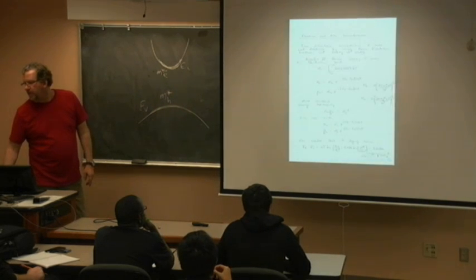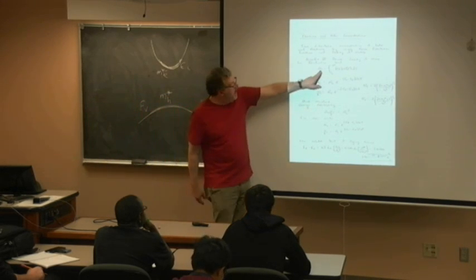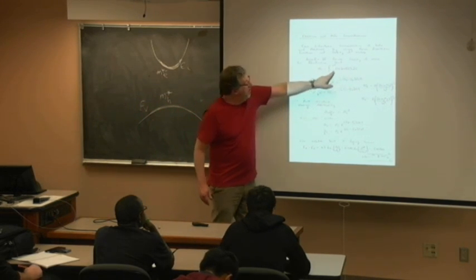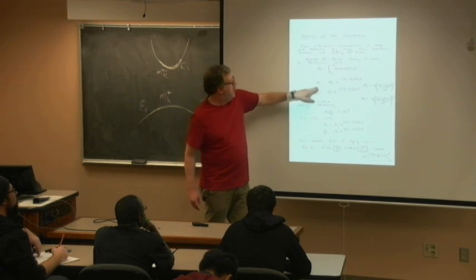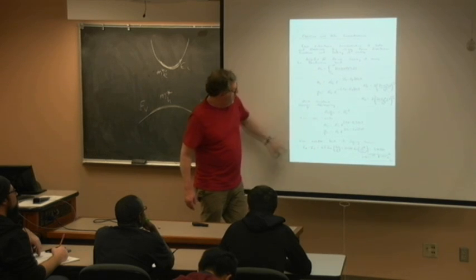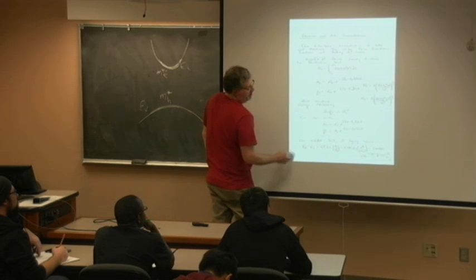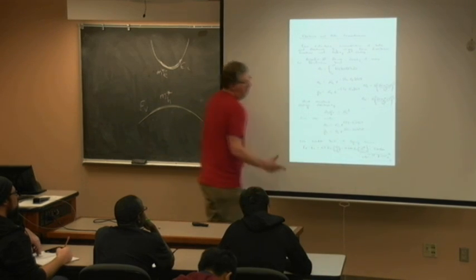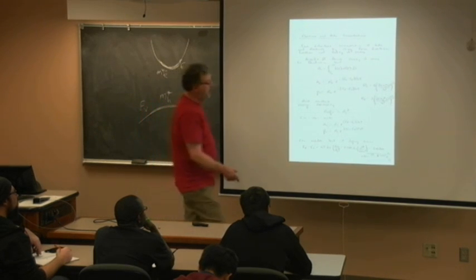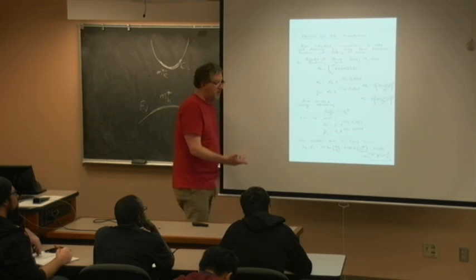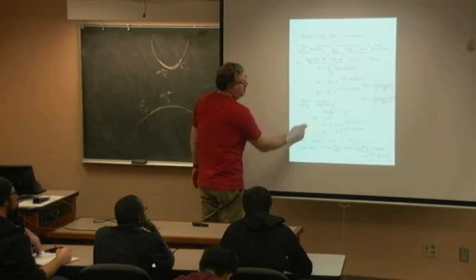And we've seen that before, electron concentration. So now we can go through these very nasty integrals, but probably we are just going to calculate the free electrons and free holes really based on this. These are the ones we're going to want to use, intrinsic carrier concentration. If we know the difference of the Fermi level from the intrinsic level, which is Eg over 2, and I know what the intrinsic carrier concentration is because I've selected my semiconductor, then I can calculate the number of free electrons and free holes.